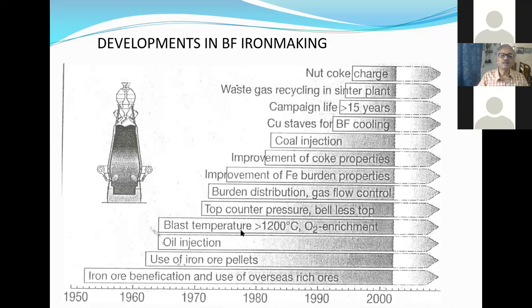And then the blast furnace hot stove is basically operated by the off gas from the blast furnace. 40% of the blast furnace off gas goes to the stove to preheat the air to 1200 degrees centigrade. And that is good. So you can utilize this own heat, and at the same time, you can reduce the coke rate. So your productivity increases.